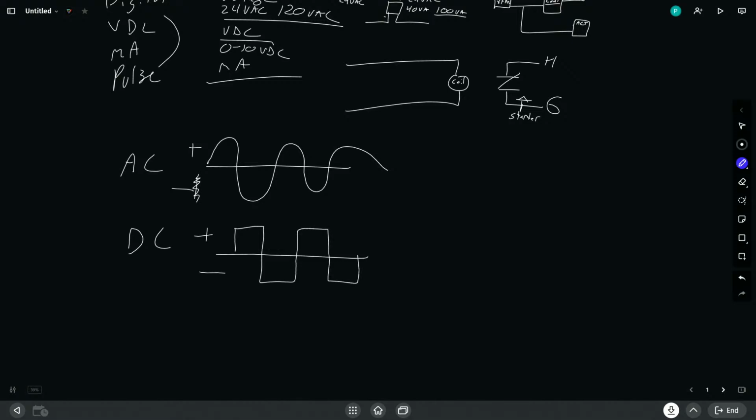And what will happen is our positive will be positive and our negative will be negative. And if we cross those wires, we are going to cause the signal to basically be inaccurate and improperly controlled and cause all sorts of issues. So we need to be cognizant of the polarity sensitivity of volts DC wiring.